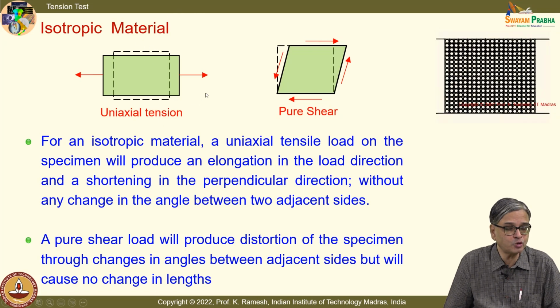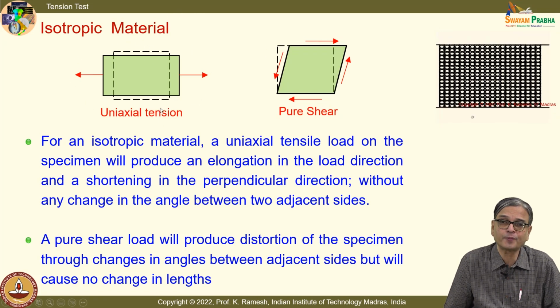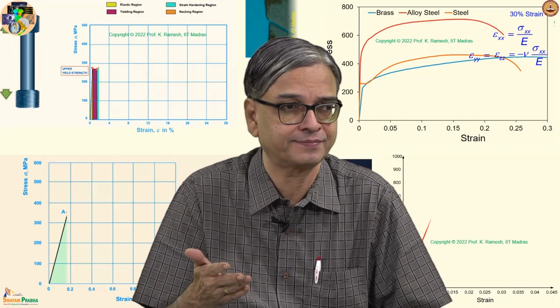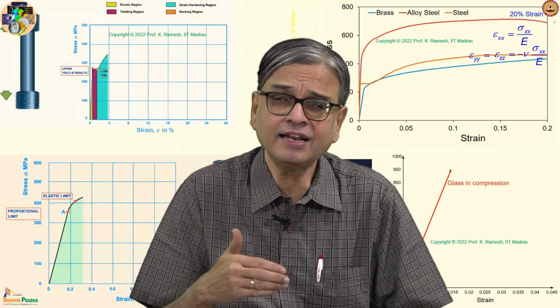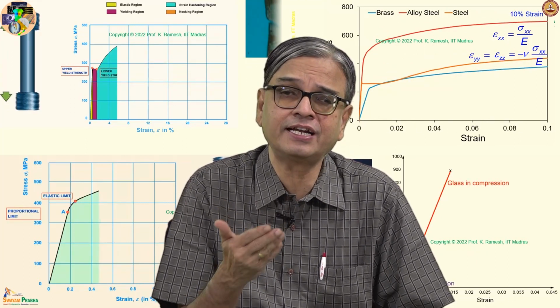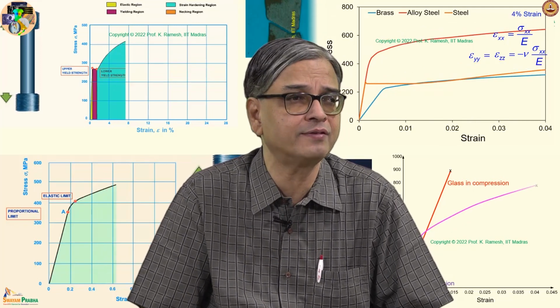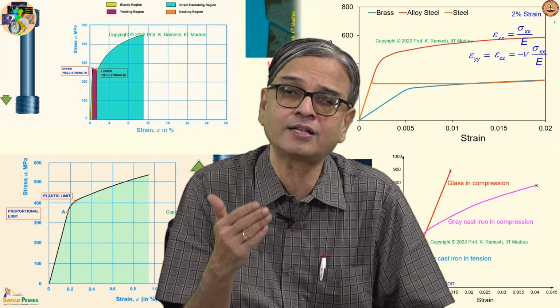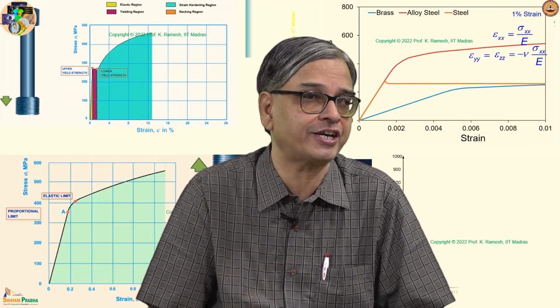So, this is a peculiarity of an isotropic material, and you know what is the meaning of isotropy. The elastic properties are identical for any direction of interest. They do not change as a function of direction. And another aspect is, we have studied state of stress at a point. You have determined the principal stresses. You have also determined what are the principal stress orientation.